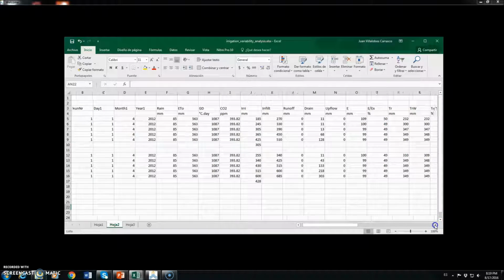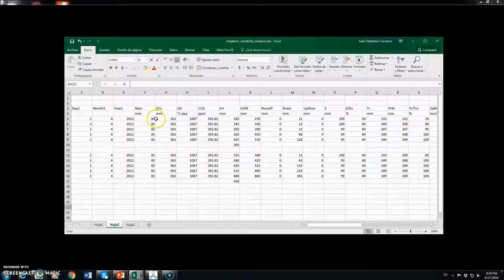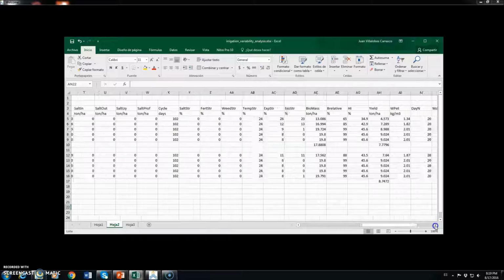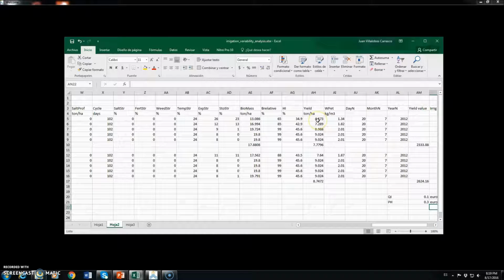Okay, according to AquaCrop, if we apply only a total irrigation of 185, we will reduce yield and get only 4.6 as compared to 9 when we apply full irrigation. Here we see that in the 5 areas of the field, in 3 of them we are getting maximum yield, but in 2 of them we have reduced yields. Why? Because we are getting not enough water for maximum evapotranspiration and maximum yield.